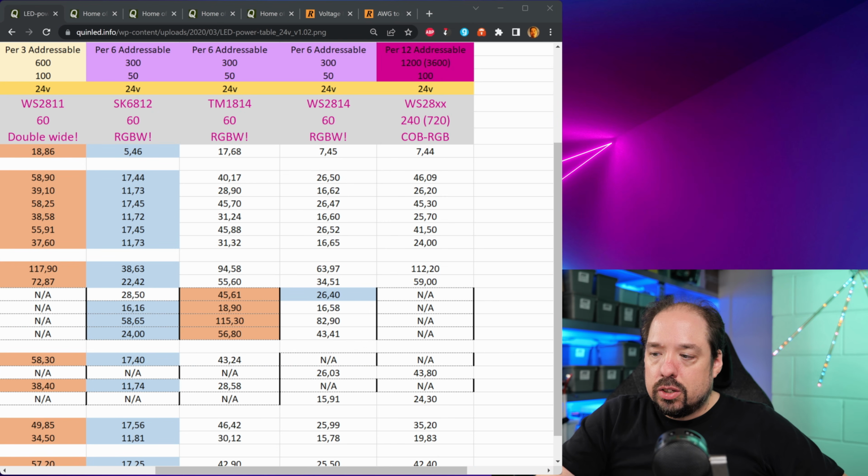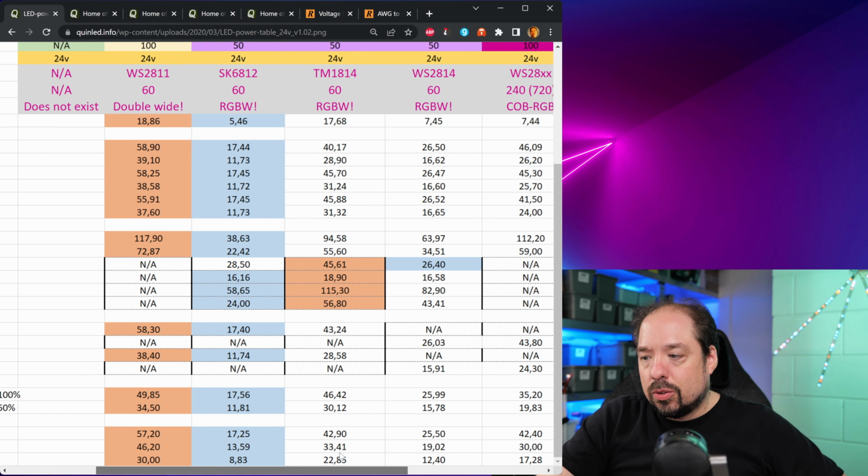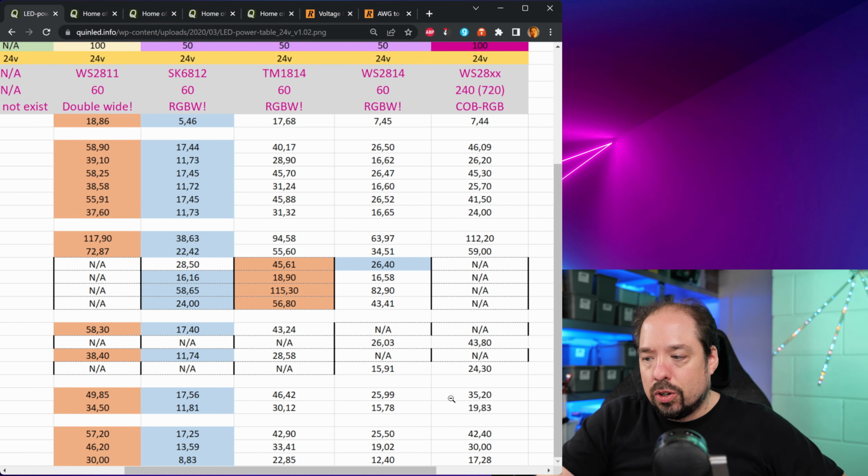We calculate with 50% white. But a single color basically uses about 45 watt. So that's already less than 60. Let's keep that in mind. And looking at the effects, none of the effects uses more than the 45 watt of a single color.